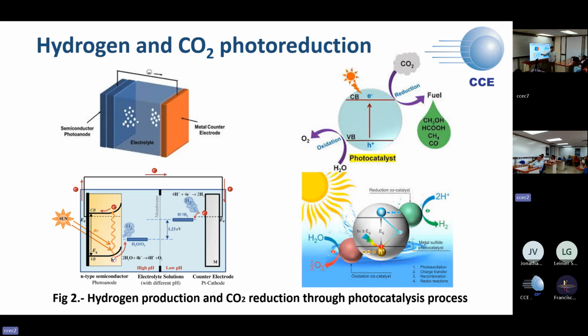In a PN junction, electrons from the N-type material go to the P-type material, and holes from the P-type material go to the N-type material, giving a positive charge to the N-type material and a negative charge to the P-type material, creating an electric field. So it works like a valve, directing the flow of the current.